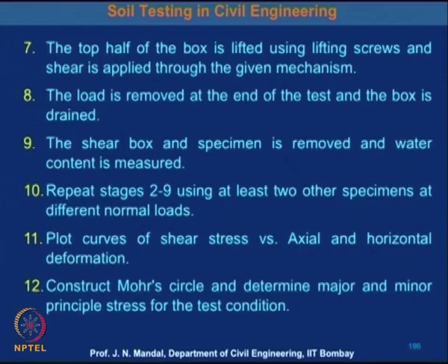So, with this kind of test you can determine the shear stress, the axial and horizontal deformation, and then you determine the major and minor principal stress under this condition. This shear strength parameter will be very useful in geotechnical engineering. Thanks.